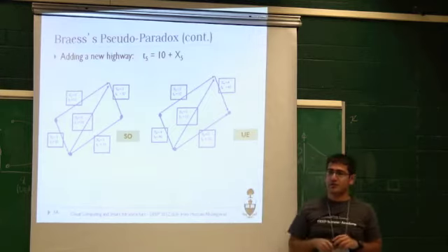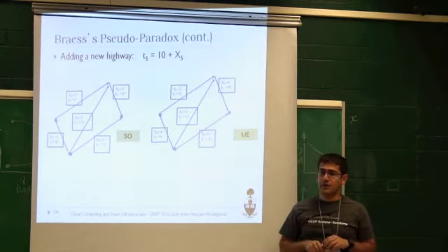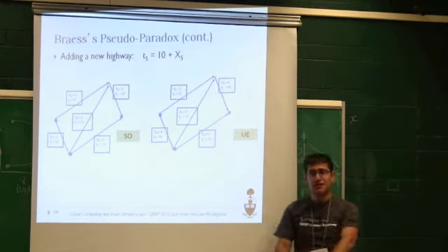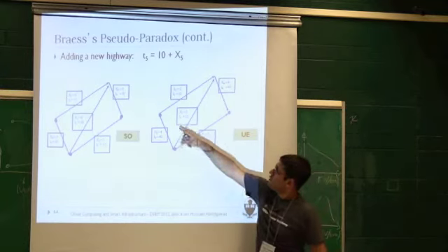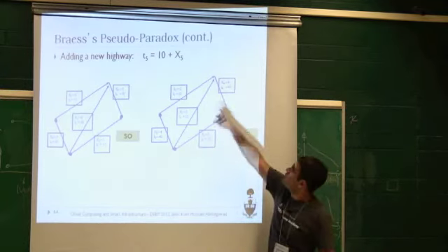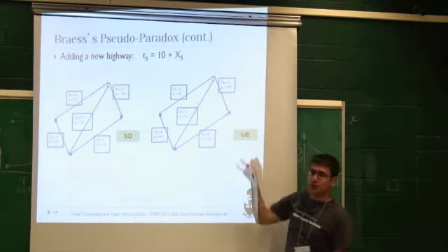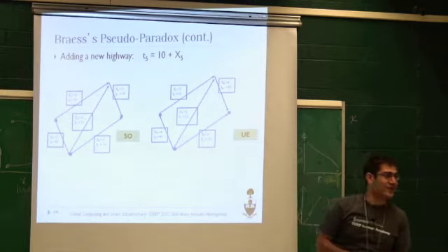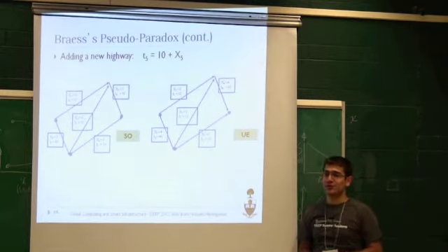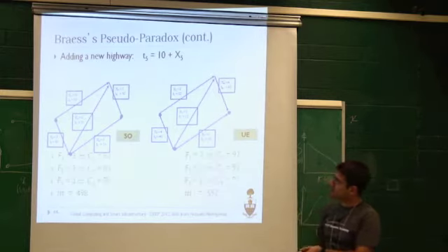Yes? Why would someone use that if it's longer though? Isn't the total travel time the same? Based on this, the travel time for the vehicle, if you go through there, it's 92. If you go through there, it's 92. And if you go through there, it's 92. Right? Based on rational behavior of drivers, that's what you end up with. So what's the travel time here?